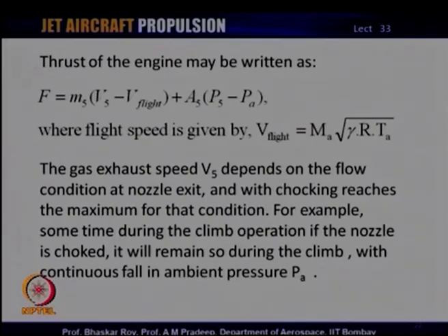And that is what I mentioned earlier, that the engine designer tries to ensure that at any given instant the engine is producing preferably the maximum possible thrust, which as I mentioned is not the maximum thrust of the engine, but for that given operating condition that is the maximum possible thrust. So, most of the time the engine should be operating under conditions that give maximum thrust for that particular operating condition, that is maximizing the use of the engine for the purpose for which it is created.